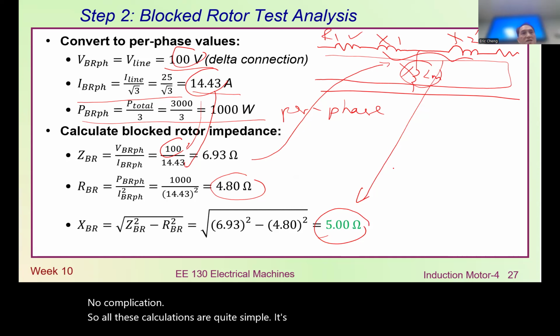From here, you see we have been using a number of estimations. We assume, for instance, this is 0.5x. We're not quite sure, depending on the motor. We also say that in the blocked rotor test, we need to use much lower voltage, low voltage to make sure the motor will not blow up or be overheated. With this low voltage, the magnetizing XM will be small, the core loss will be small. In this case, we can assume the whole current will only be looping in this R1, X1, X2, R2. So we can ignore the other component.